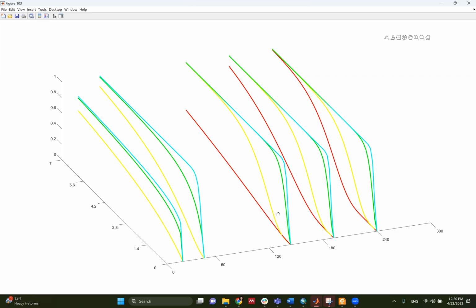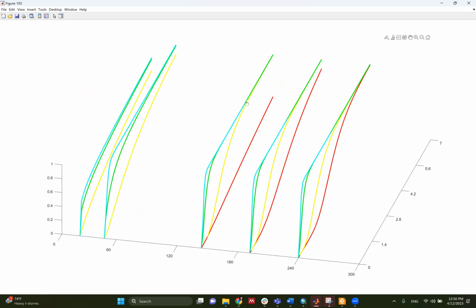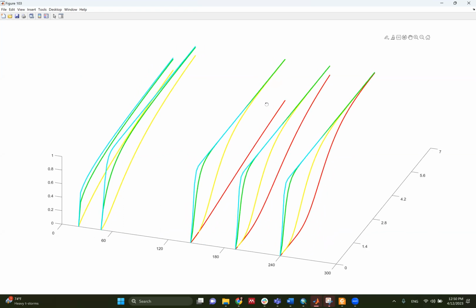But assuming that the building is soaked in water for about 6 days, the foundation is going to have some scour, you will have some serious structural damage, and then damage state 4, the red one, is going to show up. And as flood duration increases, the exceedance probability of damage state 4 increases. So this is how the 3D fragilities look.